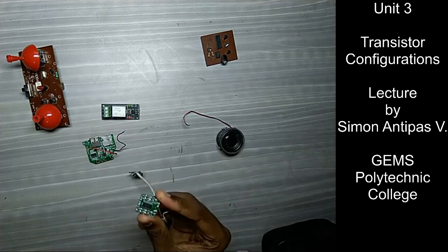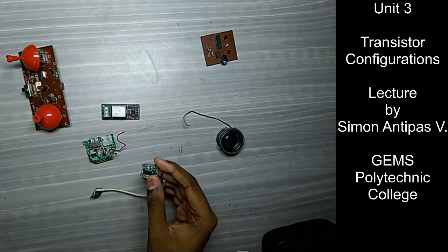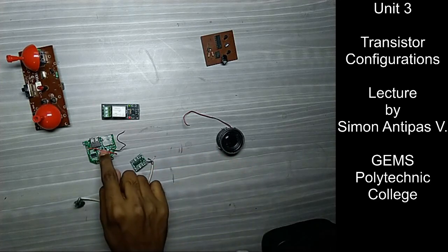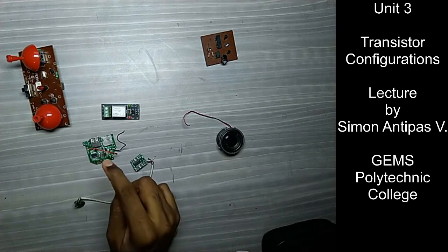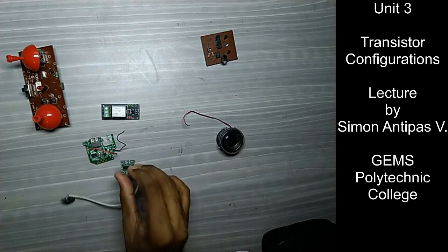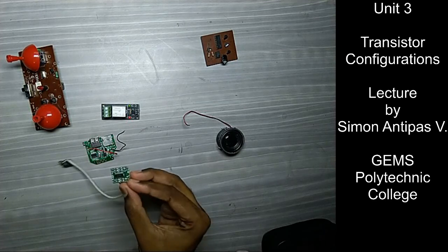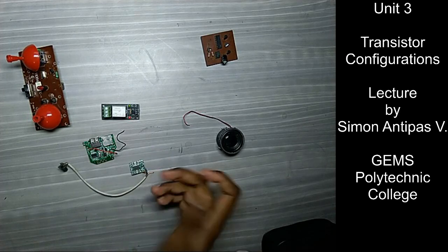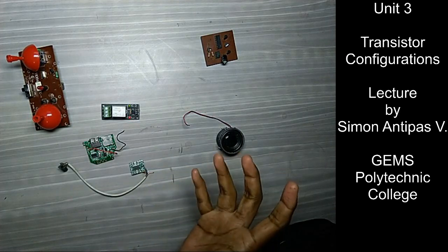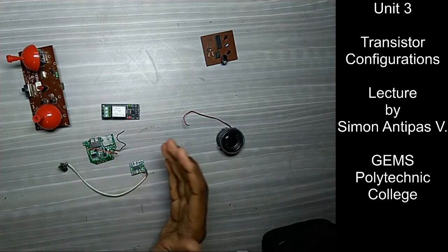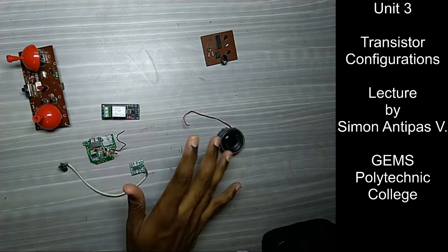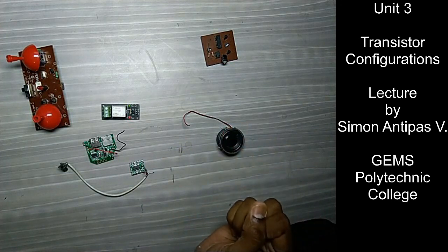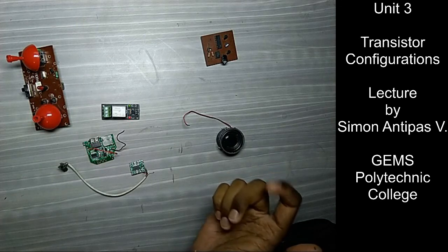So amplifiers are not big. The word amplifier is to amplify the signal, but their size does not have to be big. So I can use even a single transistor as an amplifier. I can couple 2 of them together. I could have an IC developed based on transistor-based amplifiers integrated into a single IC. So this is what you would see amplifiers as in the smaller form factor. When you're talking about bigger form factors, yes, you would have transformer-based, center-tapped, coupled, NPN, PNP combined together to be able to work on the entire spectrum band and amplification. And those we would see with practical demonstrations in the upcoming sessions.